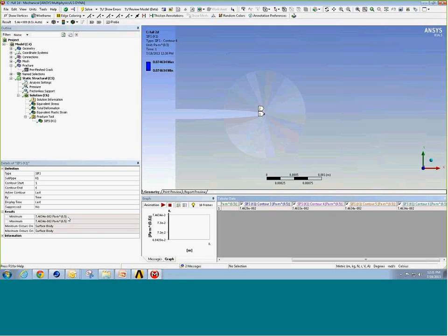And that's kind of the general procedure. That's sort of interesting, but it's only 2D, and we had to come in with our crack geometry. By the way, you could have come in with a crack mesh as well if you built something in APDL, and you could bring it through FE Modeler. You could bring in the whole mesh already with a crack in there in your complex 2D or 3D geometry. You could do that as well.